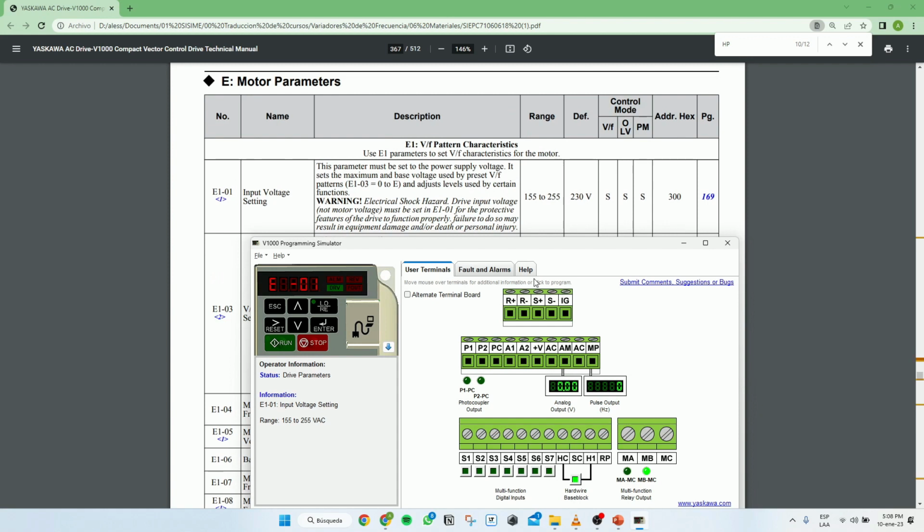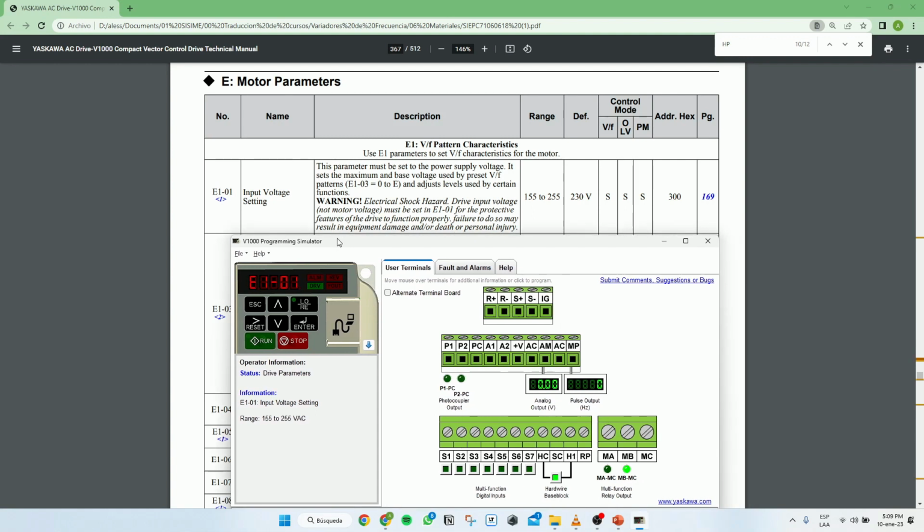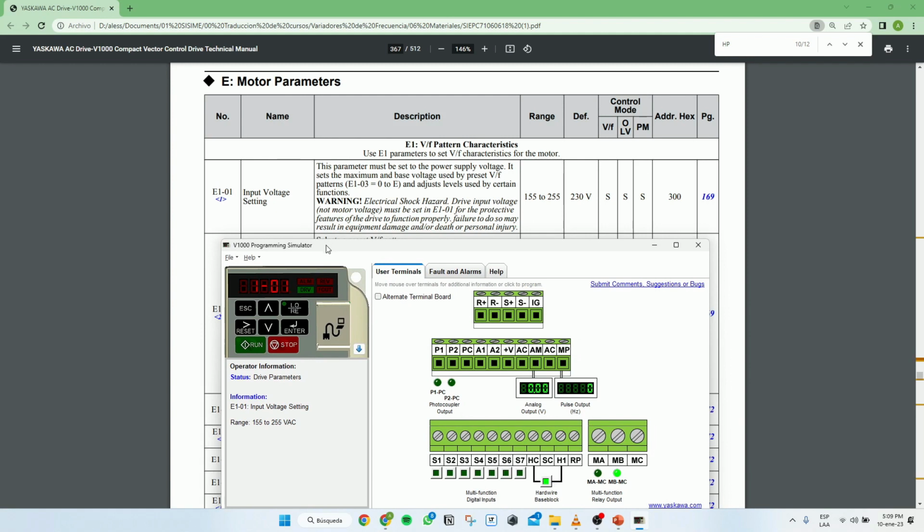Also, the drive is called different ways. It's drive in English. In Spanish, it's called frequency variator or speed variator, which both ways are correct in Spanish. And it's also called an inverter. You probably already know why it's called that, and it's because of the internal part on how it works. So any one of the four names that I'm telling you about are correct.